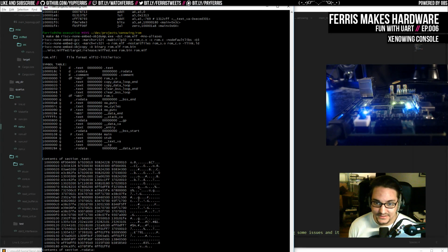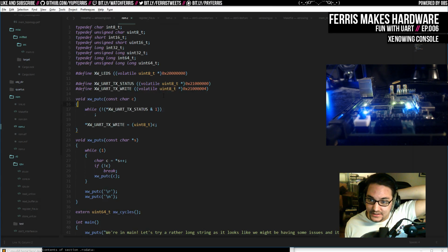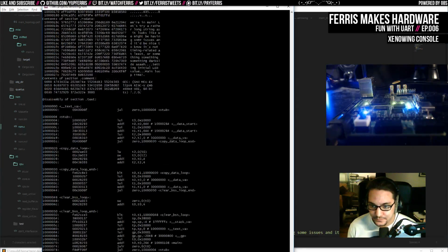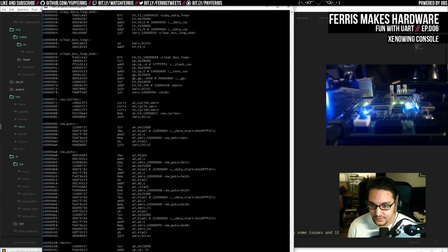In particular, I have this symbol table, and this is actually how I found that it was doing that small data thing. Those symbols were put in here, and I could see where they were in memory, and I just saw that they were in the wrong place. In this case, they don't show up anymore because I've changed them to these defines, which seems to get around that issue. They're not actual symbols anymore. These are just macros. So yeah, that gets pretty simple.